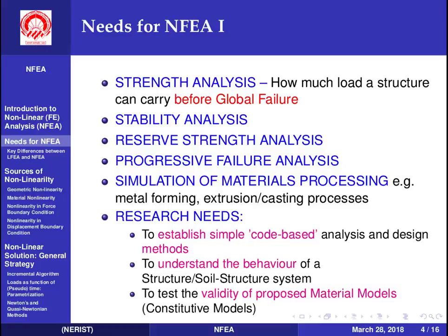Then stability analysis, then reserve strength analysis, then progressive failure analysis, how the failure initiates in a given structure, and how it progresses until the collapse of the structure. So when we want to study those things, then we need nonlinear finite element analysis, because all these problems are basically nonlinear problems.